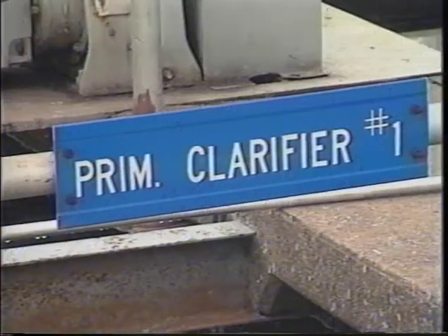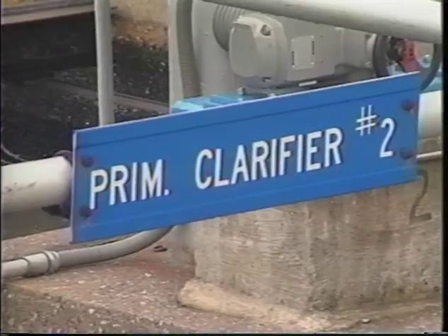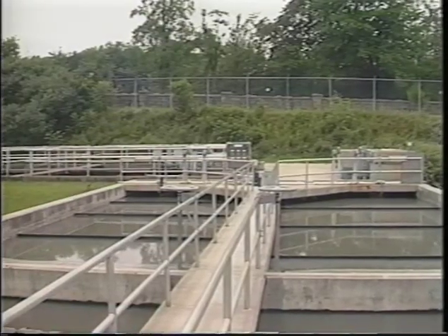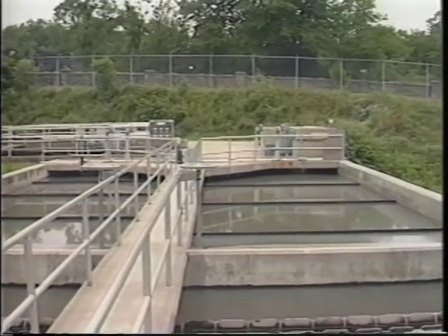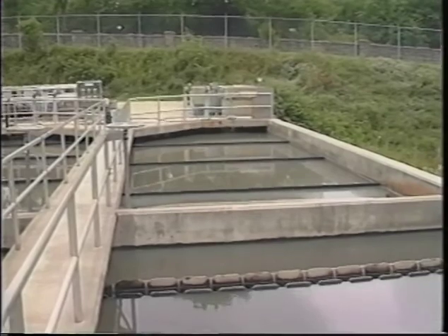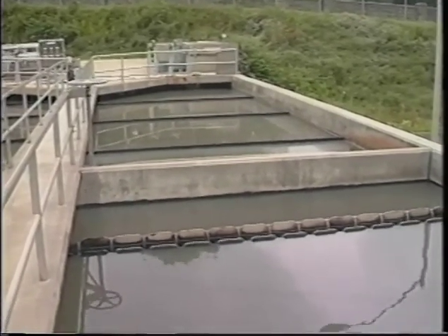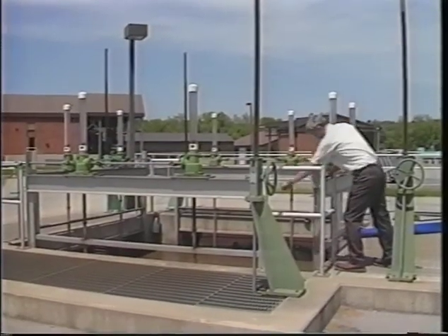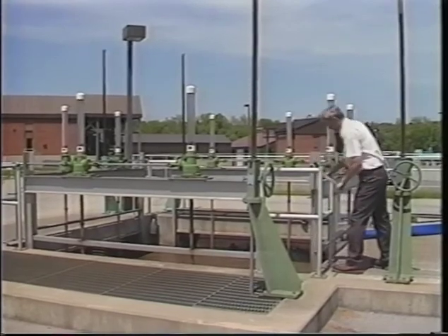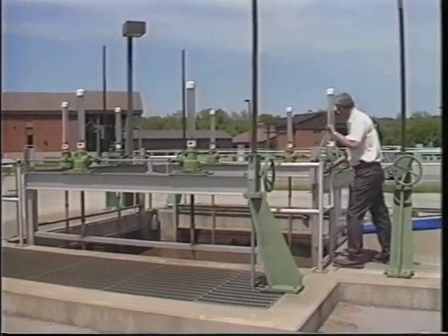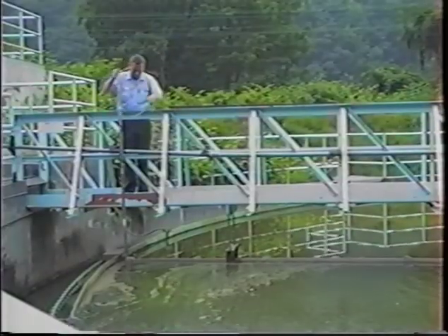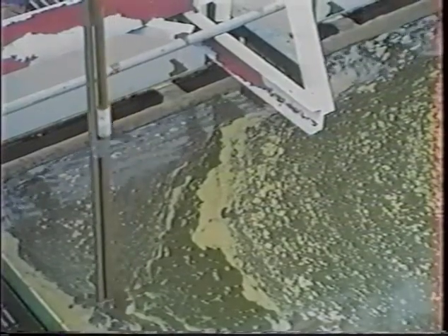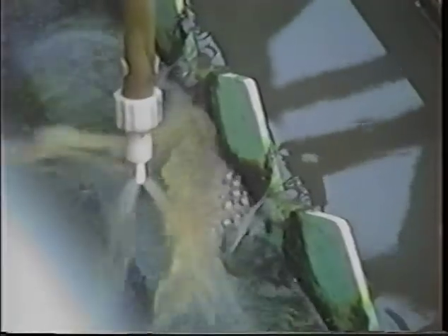When checking the influent characteristics to the activated sludge process, be sure to calculate the efficiency of the upstream treatment units. Problems upstream can lead to problems downstream. Be sure to measure all conventional parameters, including BOD and TSS. Return activated sludge rates may need to be adjusted as loadings to the facility change. Be sure to measure the TSS concentration of the return activated sludge. Using a sludge judge or similar device to monitor the depth of the sludge blanket can help you to determine when to adjust the return rates.